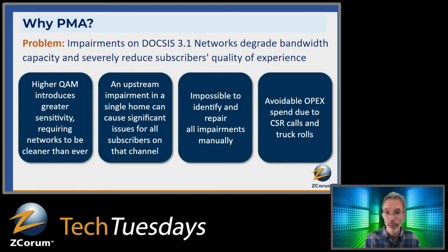If noise is coming in, say they do something on the side of their house at the NID, at the demarc point, that lets in noise, then that's going to roll upstream and impact everybody. And if you've got lots of customers out there that have little issues, then that's all cumulative. It just flows upstream and collects, and by the time it gets up to the CMTS, it can be pretty noisy. So that's just something to keep in mind.